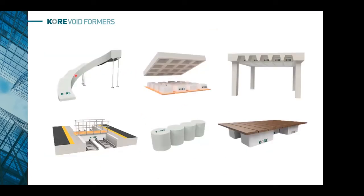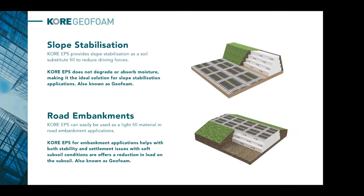And this is just, I suppose, a snapshot of some of the other ones. So trough molds, various slab requirements. If somebody wants to reduce concrete in a build-up, we can use a void former as per the specification, the size that's needed on the site. Even just temporary rail platforms, all sorts of weird and wonderful shapes can be accommodated with EPS. That's the beauty of it. It can be profiled and shaped as the project requires. So a void former would normally relate to the piece of EPS that's been used along with concrete, so under concrete.